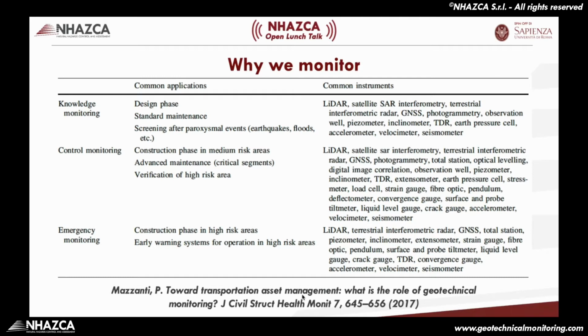Because the most important point that is rising from what I was mentioning in those sentences from Ralph Peck, John Dunnicliff, is that you need a question. If you have a question, it's not just a matter of putting instruments somewhere. It's to understand your needs, to define what is the right tool to have, the right way to analyze the data. This is what should be named design. So the design of a monitoring plan is what I think today is the most important part that must become relevant during any project, construction, maintenance, or similar.